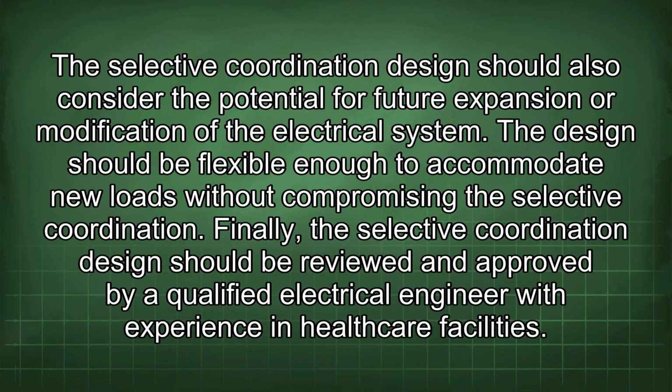The selective coordination design should also consider the potential for future expansion or modification of the electrical system. The design should be flexible enough to accommodate new loads without compromising the selective coordination. Finally, the selective coordination design should be reviewed and approved by a qualified electrical engineer with experience in healthcare facilities.